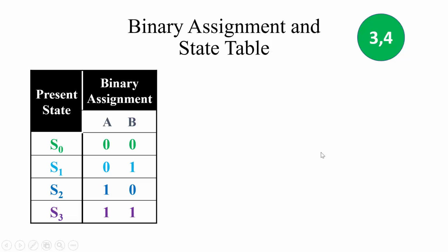The next step is state assignment, और हमने previous lectures में देखा हुआ है that we have multiple options, but we'll choose the binary state assignment which is also usually the norm. और इस केस में हम देख सकते हैं कि S0 को हमने 00 बाइनरी कोड असाइन कर दिया, S1 is 01, S2 is 10 and S3 is 11, and we can also determine from here that we'll require two flip-flops जिनके state variables के नाम हमने A और B determine कर लिए to implement our design.